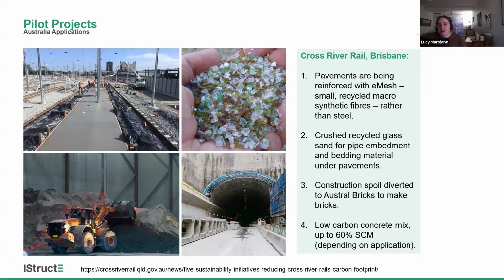And then coming back to our SCM, our supplementary cementitious material, depending on the application, up to 60% SCM can be got into the concrete mix. Now, you'll definitely find that state by state, the state government specification guidelines will really govern that. And there's a whole another presentation probably around the nuances of concrete mix design for lower carbon outcomes. That could be an idea for a future talk.